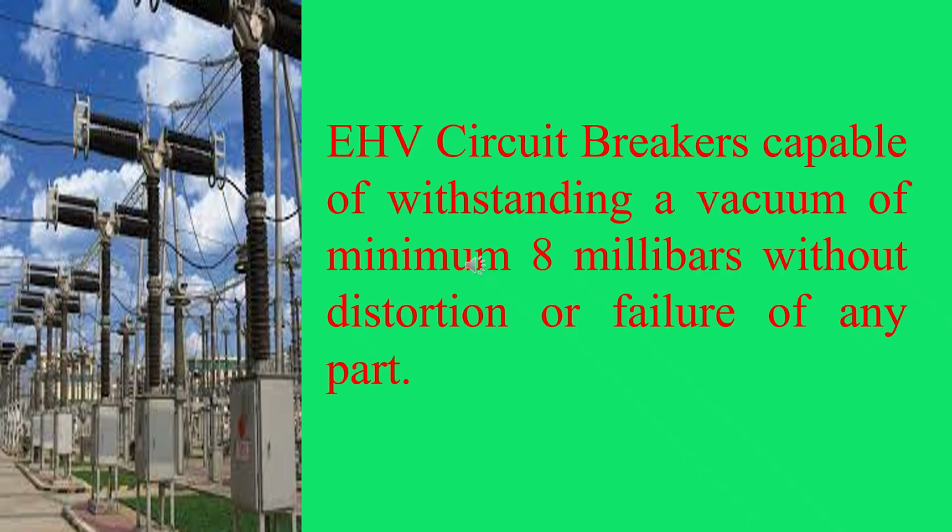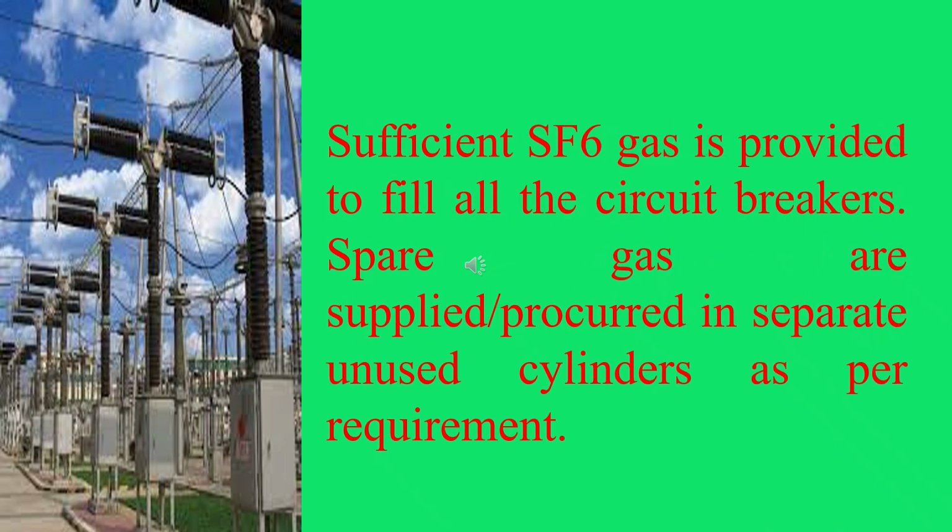EHV circuit breakers shall be capable of withstanding a vacuum of minimum 8 millibars without distortion or failure of any part. Sufficient SF6 gas is provided to fill all the circuit breakers. Spare gas is supplied, procured in separate unused cylinders as per requirement.